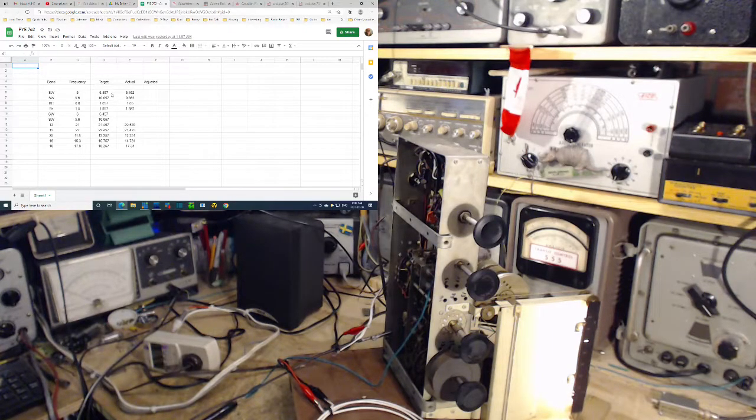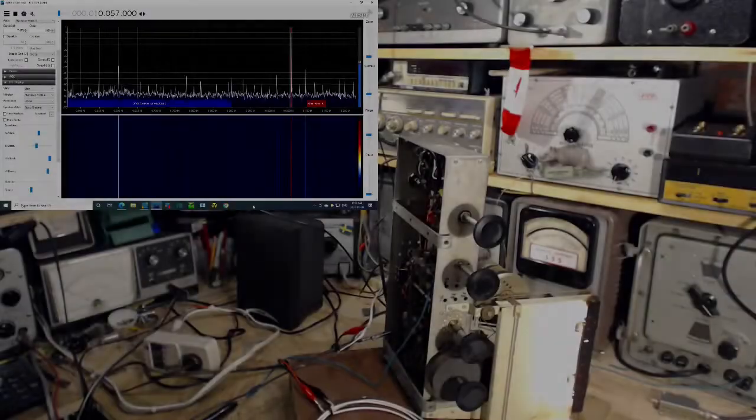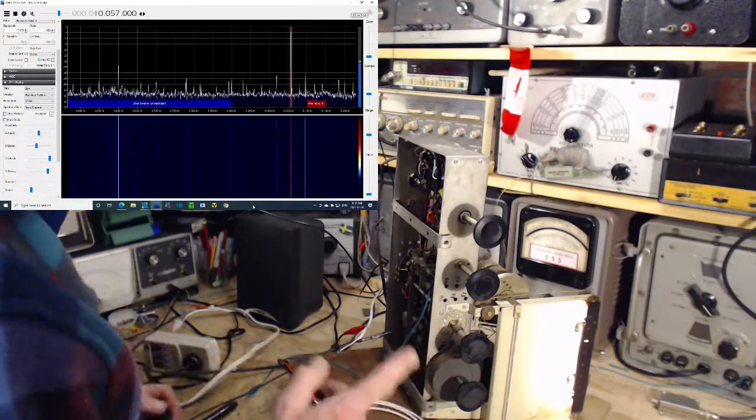What am I going to prove? You know what? I can't prove this. There's a weakness here in how I'm doing this. If I tune the radio now so the local oscillator is at 6457, I no longer know for sure it's pointing at 6 megahertz. I gotta stop for a bit and think about this. There is a problem with doing it the way I was doing it, but I know how to get around it now.